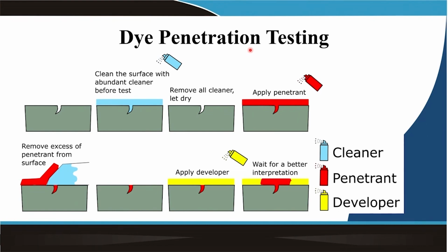If it is a very thin oxide, you can go for alkaline dissolving. For example, if aluminum oxides or titanium oxides are there, you can go for typical caustic soda cleaning.